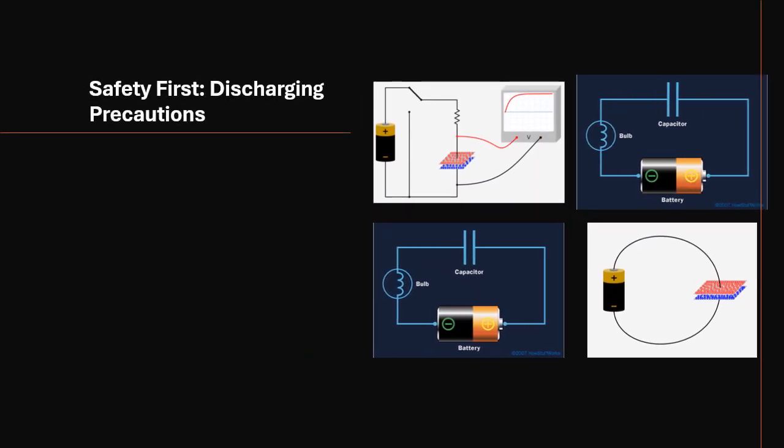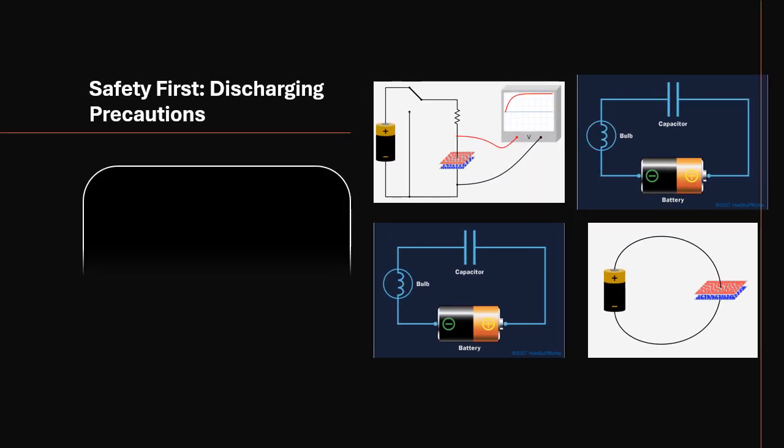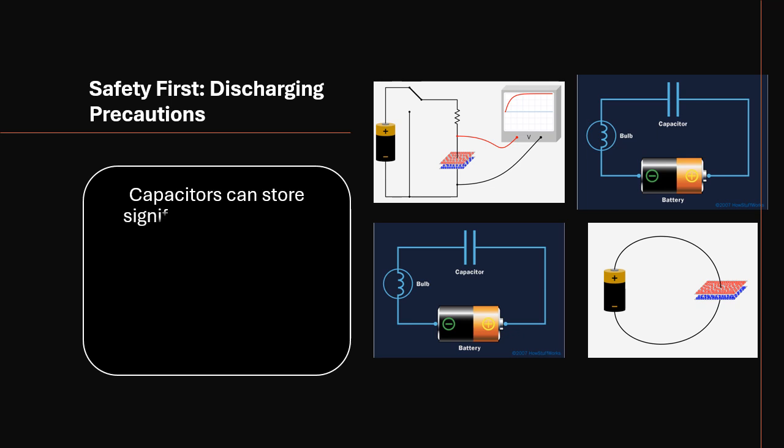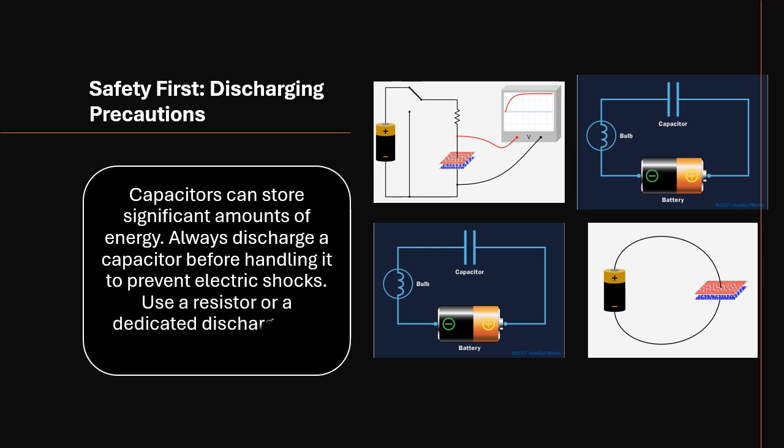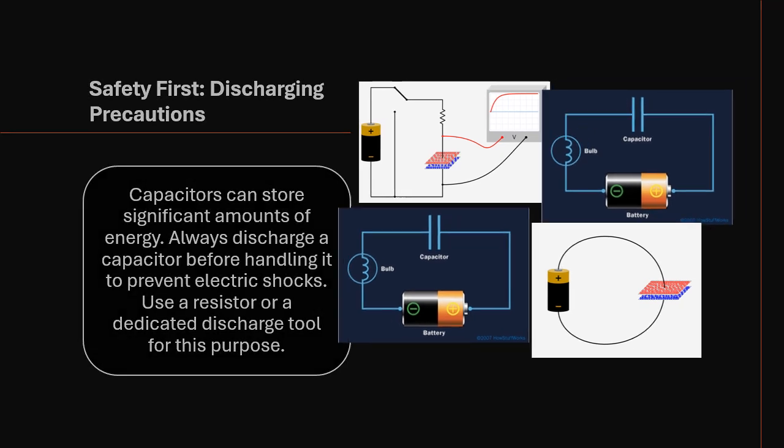Safety first, discharging precautions. Capacitors can store significant amounts of energy. Always discharge a capacitor before handling it to prevent electric shocks. Use a resistor or a dedicated discharge tool for this purpose.